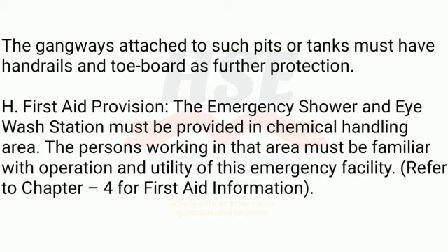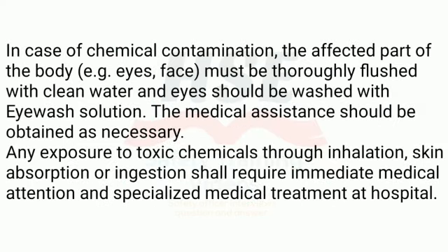H. First aid provision. The emergency shower and eye wash station must be provided in chemical handling area. The persons working in that area must be familiar with operation and utility of this emergency facility. Refer to Chapter 4 for first aid information. In case of chemical contamination, the affected part of the body, for example eyes, face, must be thoroughly flushed with clean water, and eyes should be washed with eye wash solution. The medical assistance should be obtained as necessary.